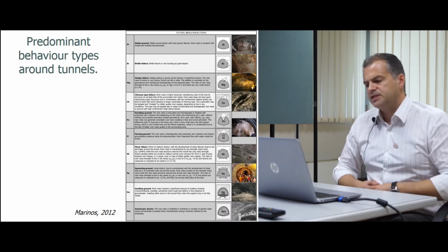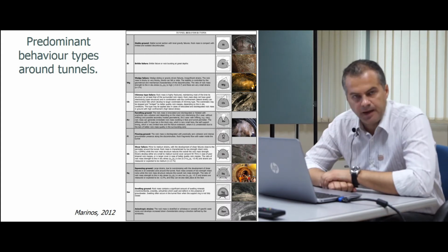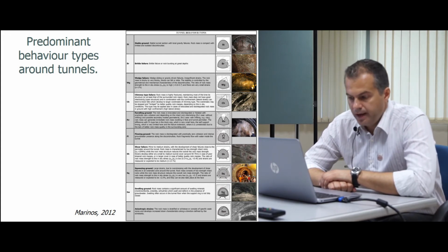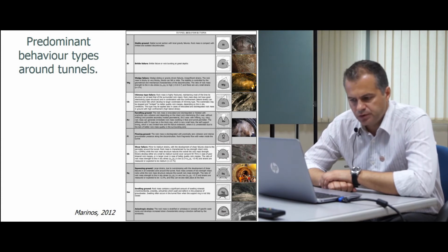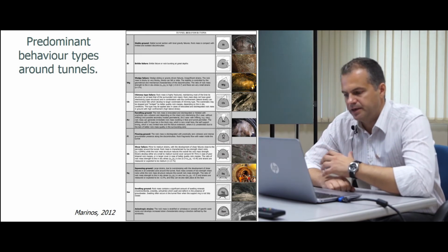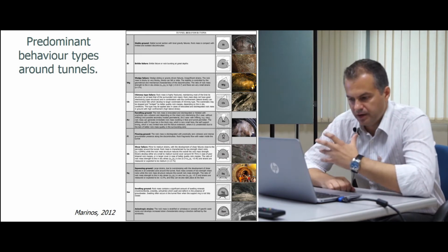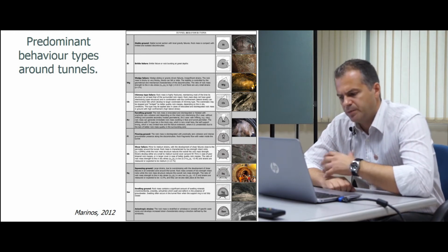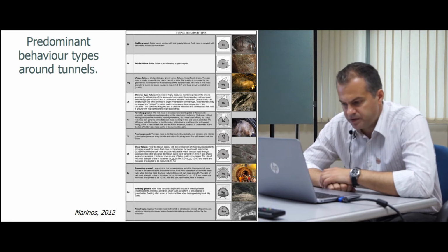The next gravity-driven failure mode is a chimney-type failure. Here the rock mass is highly fractured, but maintains a lot of the time its structure, maybe not immediately around the tunnel, but in the surrounding mass, so it can bridge these gravity-driven failures.